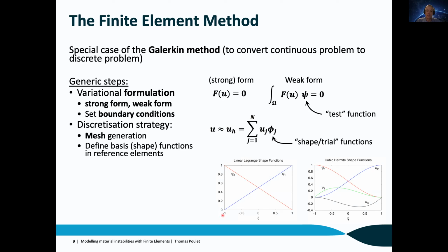For example, in a one-dimensional case, you have an element that is between -1 and 1. And then you would decompose it on 2 functions, one that has a value of 1 on one node and 0 on the other, and reciprocally for the other side. And you can see how you can write an interpolation of your function based on those 2 simple functions.